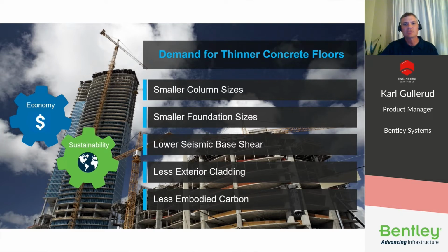Today, climate change concerns are forcing structural engineers to consider sustainability goals with their designs and look for ways to limit the use of construction material. For concrete buildings, this has increased the demand for thin post-tension concrete floors with lower reinforcement ratios. And it has also forced engineers to consider other technologies like voided concrete slabs and steel fiber reinforcement.